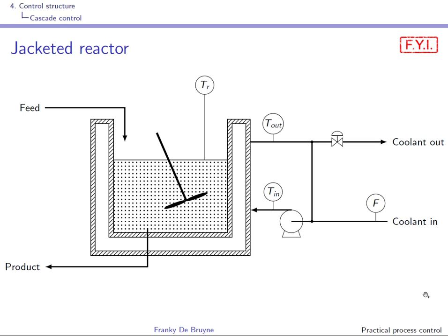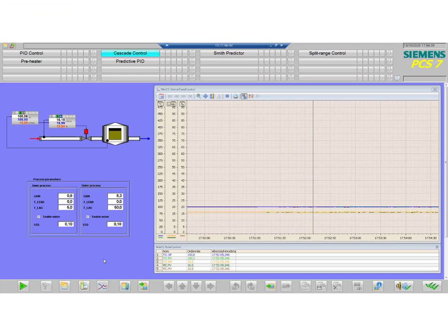cascaded solutions are investigated, and the solution that will have to be taken will depend on the load disturbances that affect the system. So let us come back to this cascade control that we have considered already before, when we had considered different cycle times. Here the outer process has a time constant of 50 seconds and the inner process has a time constant of 5 seconds. So you can see that this inner time constant is much lower than the outer time constant.